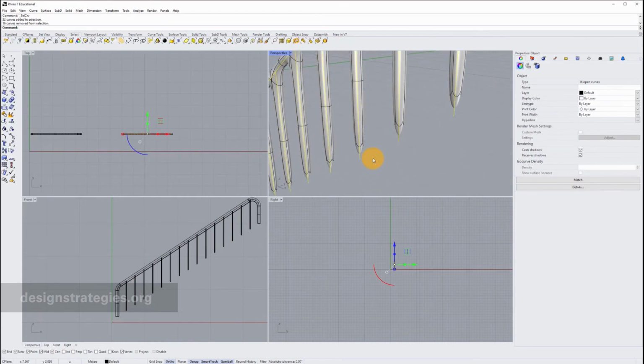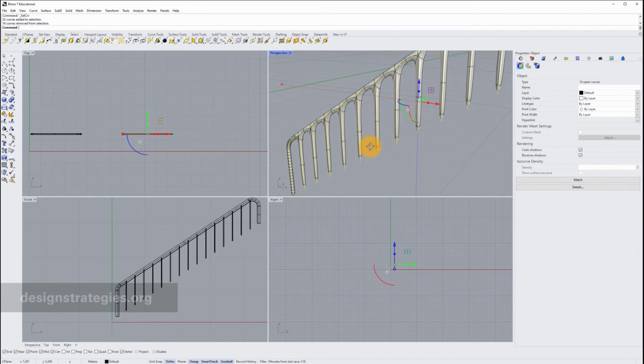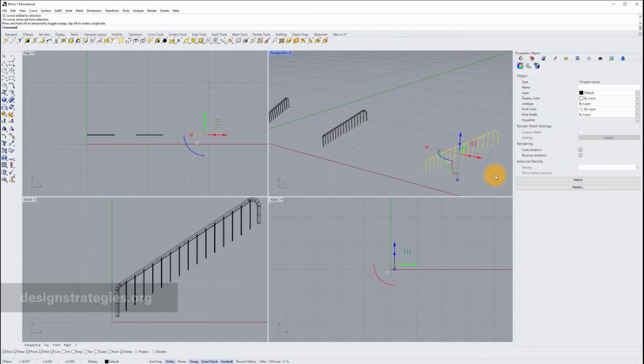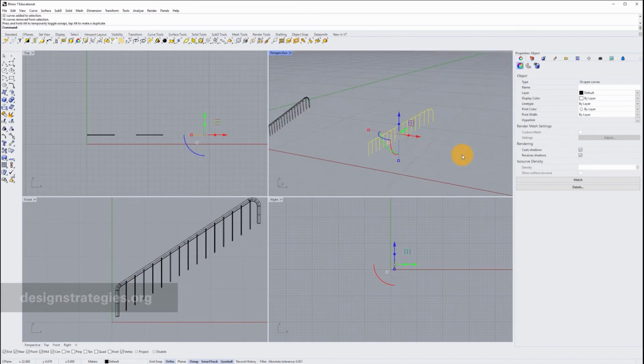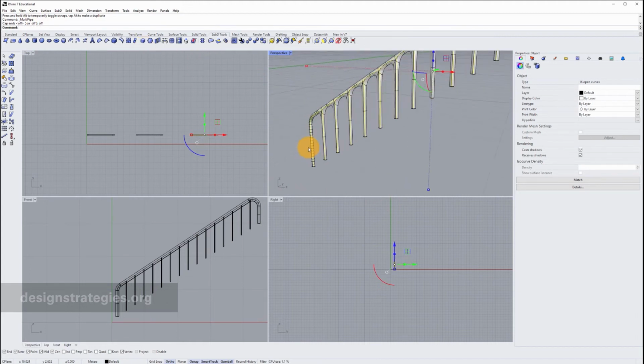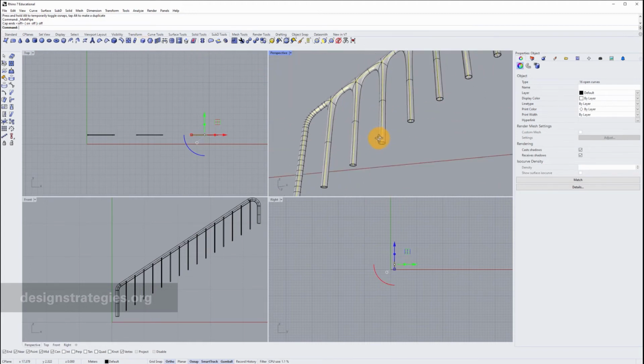And you just saw that here in the lower area, this doesn't look good. So we change the setup again a little bit. I just move my curves to the right, somewhere like this. And I just use again my subdivision tool, my multi-pipe, my radius, and here I just say cap ends off. And this already looks much better.